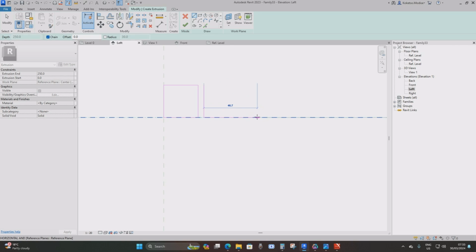and then from this point we're going to take it to the right by 45 millimeters, and then take it upwards by 15 millimeters, to the right by a further 15 millimeters, and then take it down by 7.5, take it to the right by 10, and then take it upwards by 15, press escape, and then from this point you're going to take it to the right by 60 millimeters, and then diagonally until you meet this insertion point.